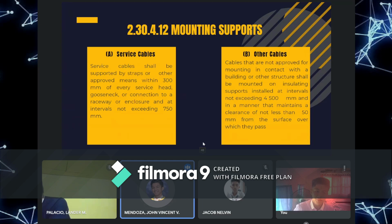So next, sa other cables naman, cables that are not approved for mounting in contact with a building or other structure shall be mounted on insulating support installed at interval not exceeding 4,500 millimeter and in a manner that maintains a clearance of not less than 15 millimeter from the surface over which they pass.